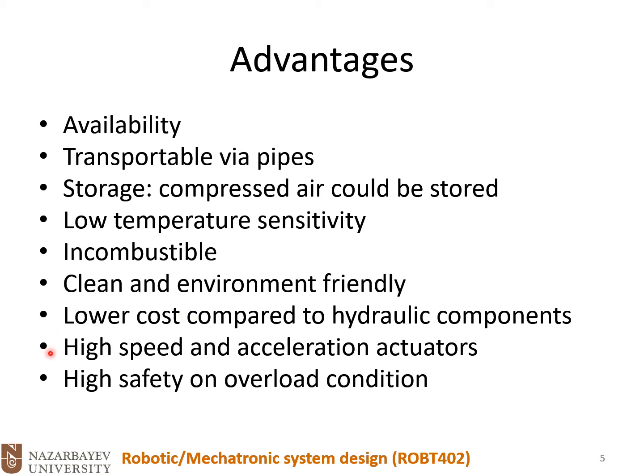High speed and acceleration actuators. That's why we should be careful once we are working around pneumatic actuators, because they move very fast with high acceleration. And high safety on overload condition.